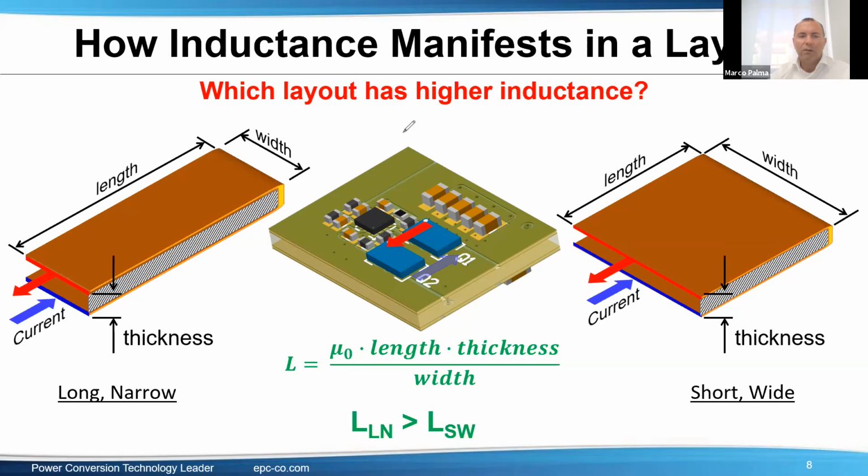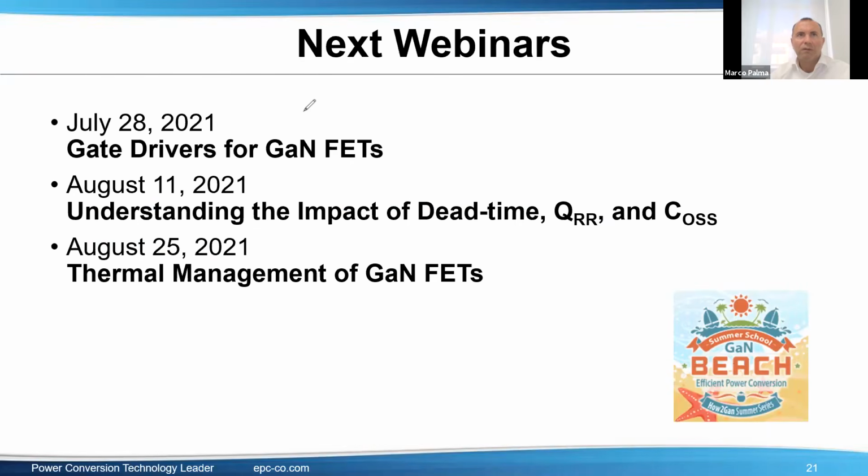Even if you want to have a 0 ohm resistor, then put 0 ohm. That's important. This will be the discussion of the next 2 weeks, exactly about gate drivers. The reason is you have to have the cleanest possible path to the gate with the resistors and nothing else.